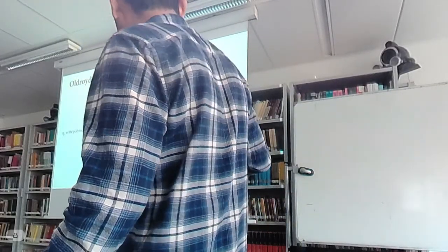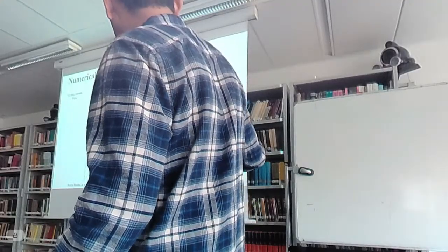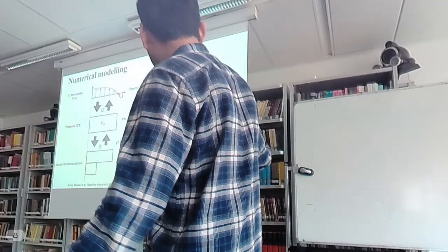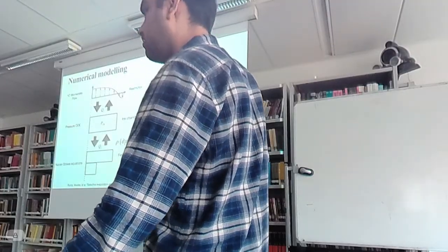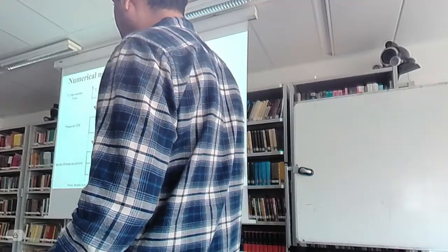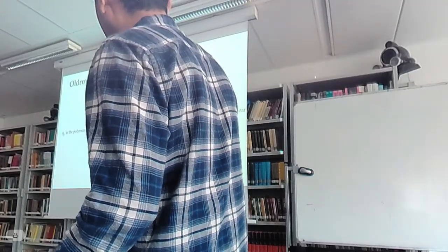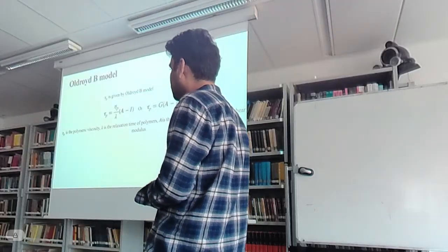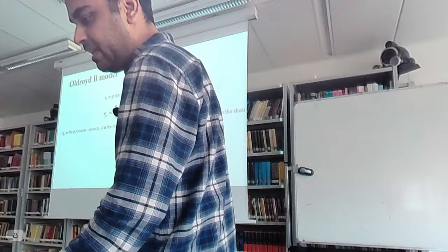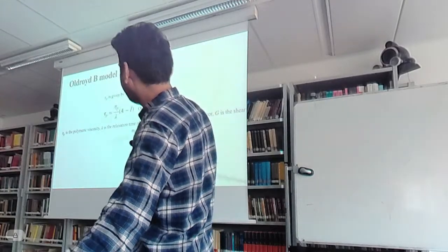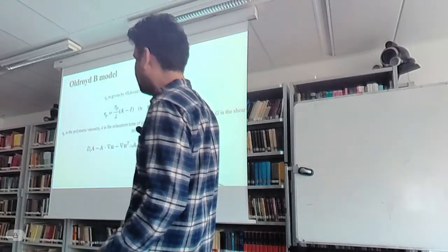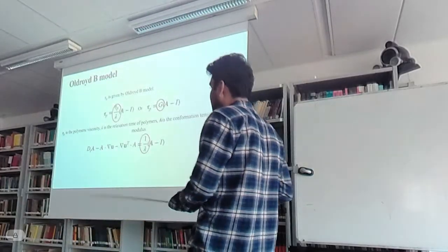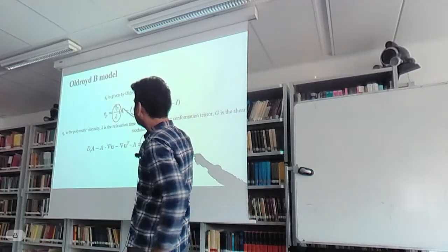We have these extra stresses in Navier-Stokes which come from the viscoelastic nature of the ink, for which we use the Oldroyd-B model, where the stress is related to the conformation tensor linearly, and this conformation tensor A follows a relaxation equation which is given here.